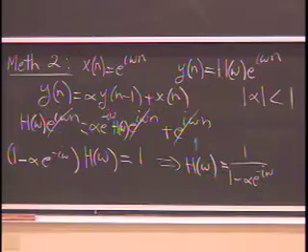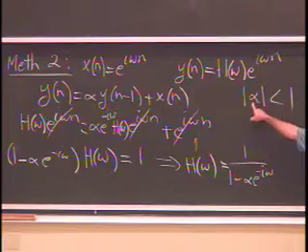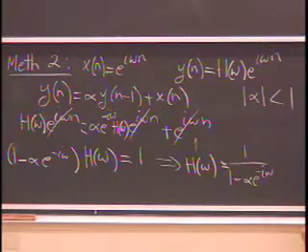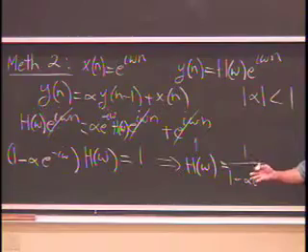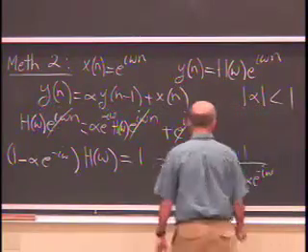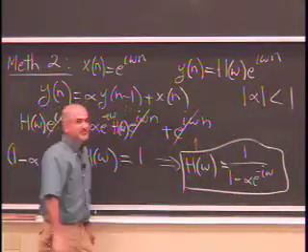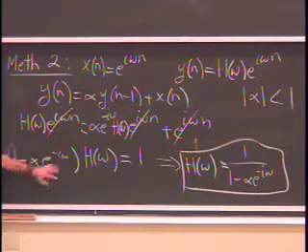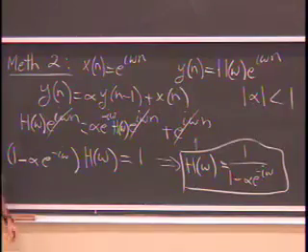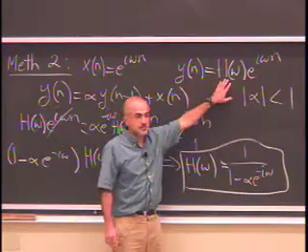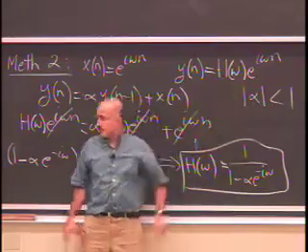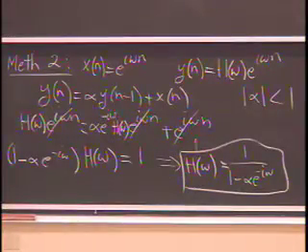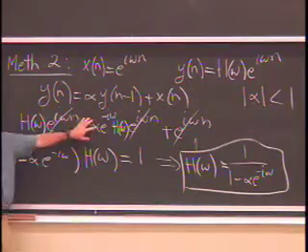Let me guess what you're going to ask. You're going to ask, we didn't even use the fact that alpha is less than 1 in this equation. Tell me I'm good. There's an implicit assumption in going through this derivation, and that is that the H of omega, the frequency response, exists, meaning that this infinite summation converges. That's an embedded assumption when you go through this method.